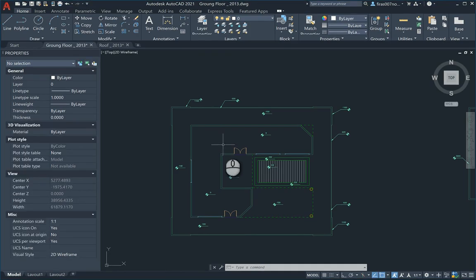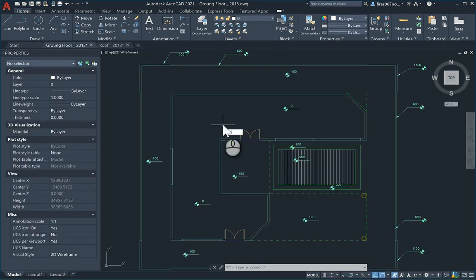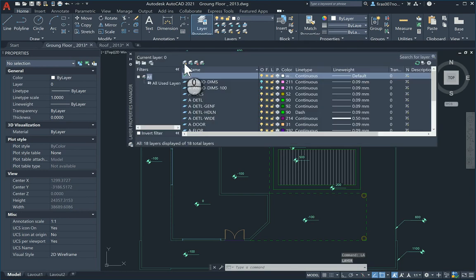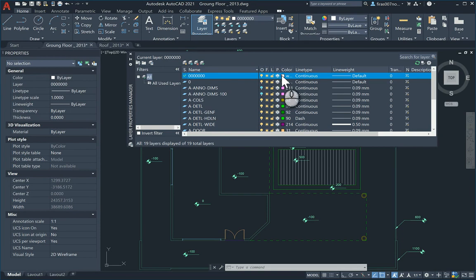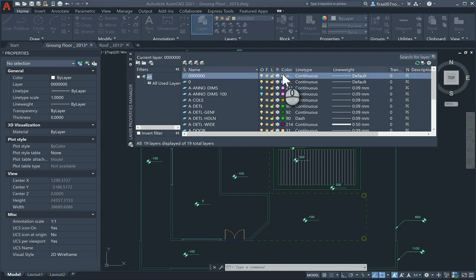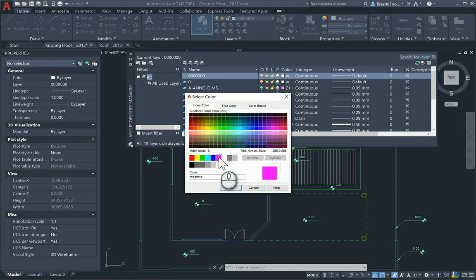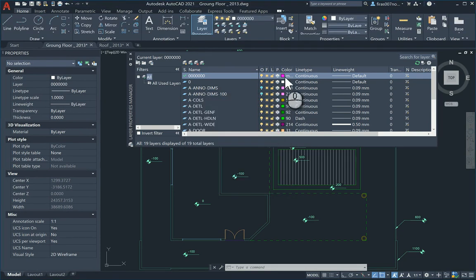Alright, so now create a new layer, LA, and then space. I'm going to create a layer here. I'll call it lots of zeros, so that will represent the active top layer. Just double click here so it will be active. Give it the ugliest color you want. For me, I think magenta. It's good to pick something eye-catching, so when you send it to Max, it will immediately pop up. Don't choose white or yellow or blue. Step by step you'll understand why, because they are the default colors for selected and non-selected objects.